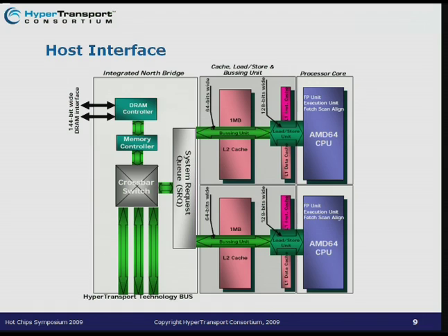So instead of directly attaching the DRAM controller to those cores or to the cache controller, in modern chips there is a unified system request queue or system request interface that gathers all of those requests from different cores and channels them through a single interface so that they can later reach a DRAM controller in the same chip, or through those HyperTransport links they can access the DRAM controllers in neighboring chips. In doing so, it's necessary to be able to route those packets appropriately. So this system request interface will handle that situation by building packets and making sure that those packets contain some routing information. So those packets could be sent through this crossbar switch and possibly other switches at different processors so that they finally reach the corresponding DRAM controller and access the corresponding cache line and bring it to the cache. Okay? So it's no longer the case that those DRAM controllers just need a memory address.